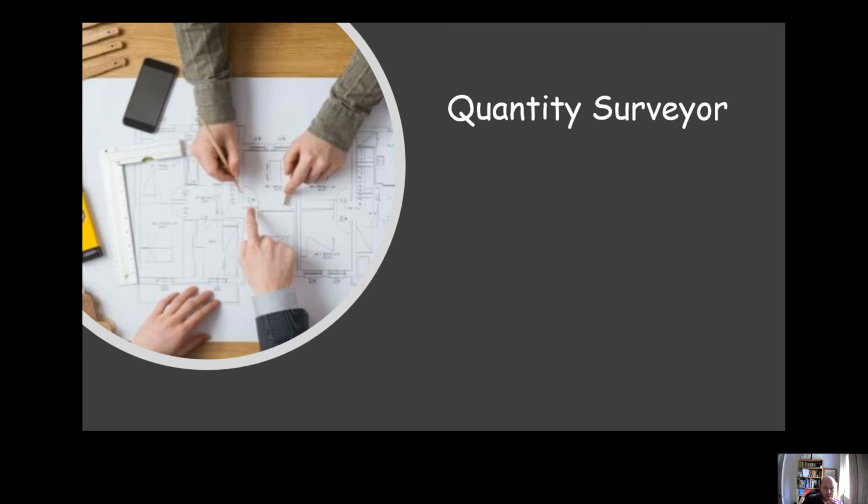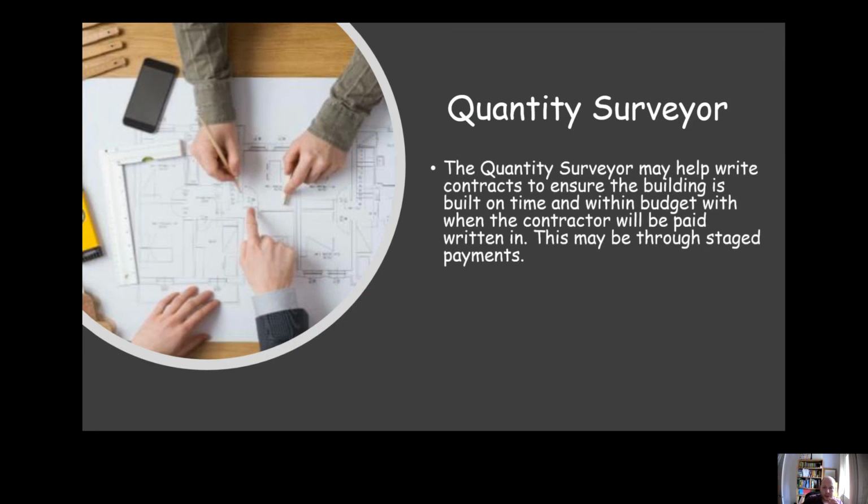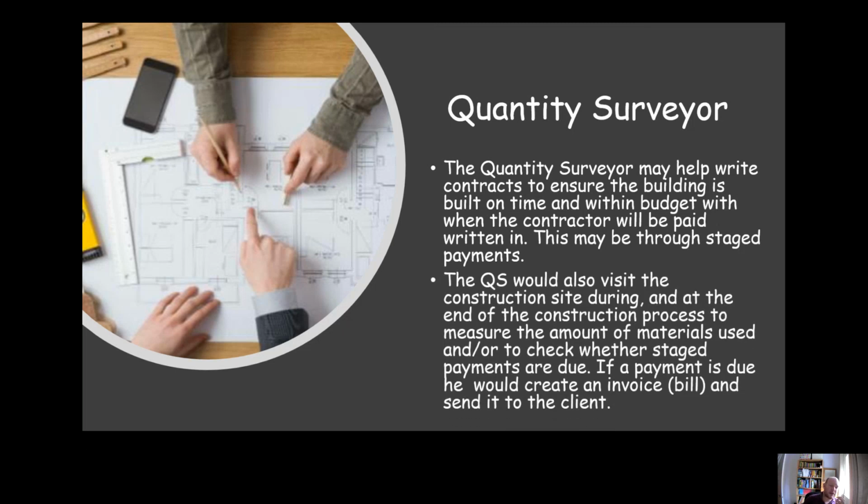Quick look at the role of the quantity surveyor. Okay, quantity surveyors are involved in writing the contracts, checking that the building stays within budget, and agreeing staged payments. This is built right into the contract, so that when the building work reaches a particular stage, there'll be a payment made. Say, once all the foundations are in, there might be a payment made.